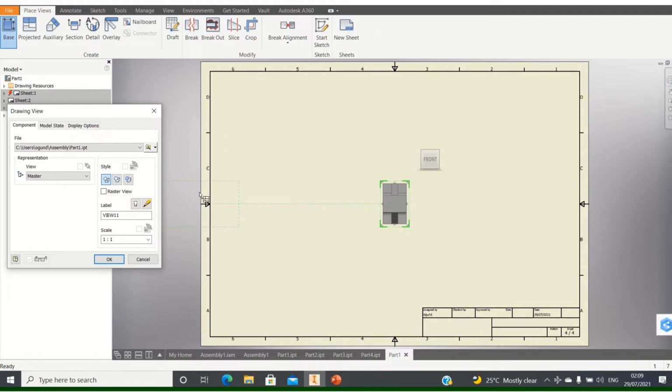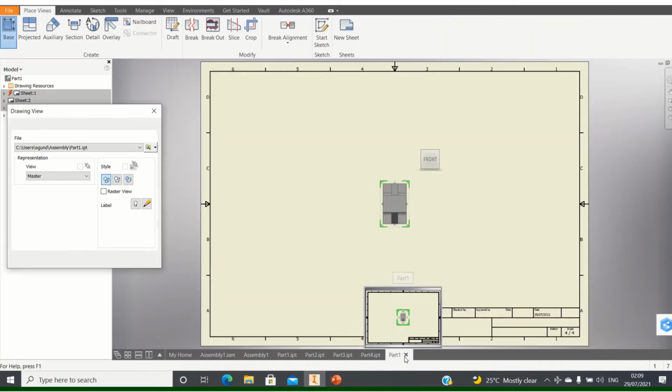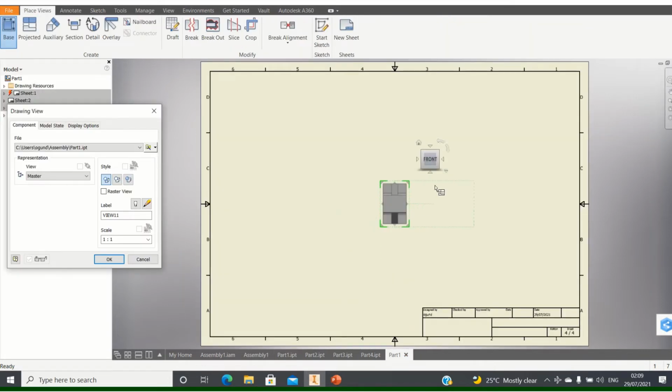Now, under sectioning, you should know exactly what you want. I'm going to produce only the plan view, as my front view on Inventor, because that's how Inventor will understand how to do the sections, since this object is sectioned from the plan view.